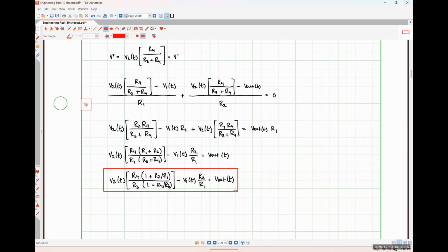No, it needs to. Yes. What do they need for? So the sensors that you usually use in actual control systems typically aren't able to supply their own power well. So you need the buffer amplifier to maintain that signal to feed into this guy. So for the exact same reason you'd use any unity gain buffer amplifier.